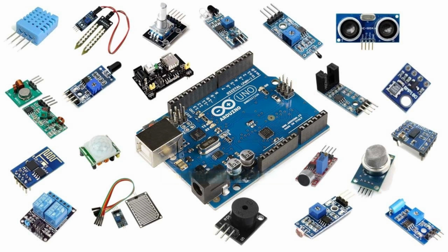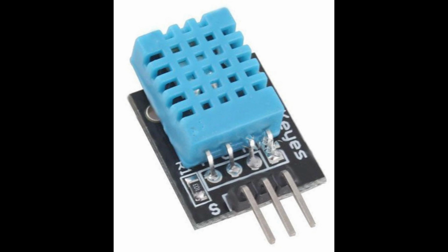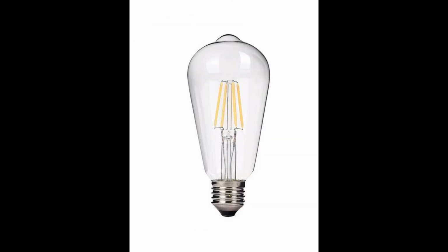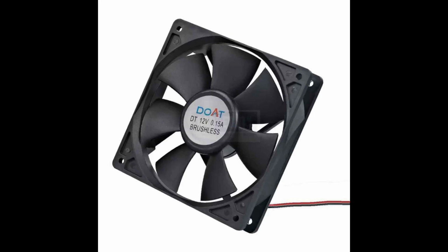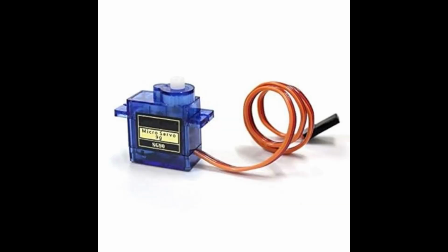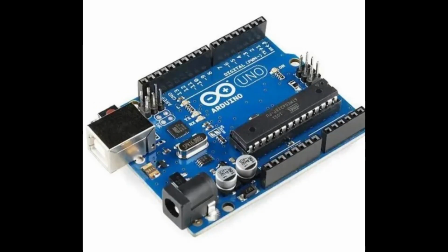In our prototype, we used microcontrollers as a cost-effective alternative to expensive hardware components like heaters and coils. We used a DHT11 temperature and humidity sensor to monitor the temperature and the humidity inside the incubator, a 25-watt filament bulb for regulated heat generation, a 12-volt DC fan to circulate the air inside the incubation chamber, and the SG90 servo motor-powered egg-turning tray to turn the eggs 4 times per day. All the components in the system are controlled by the Arduino UNO board.